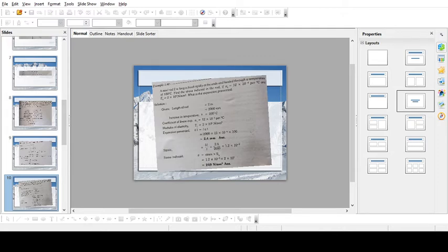Right? So that is equal to 2.4 mm. So by 2.4 mm of length has been shortened due to this. Okay. Next, strain. So strain is simply change in length by original length. So what is the change in length? 2.4 by 2000. So that is equal to 1.2 into 10 to the power of minus 3.